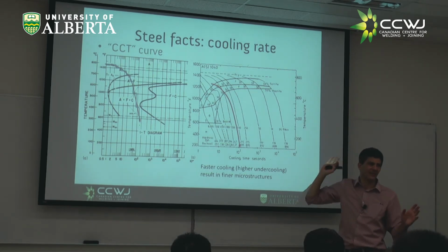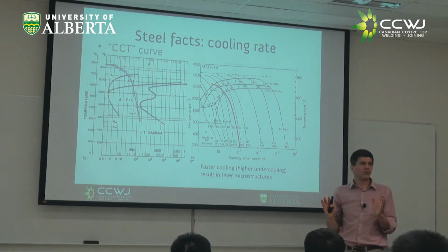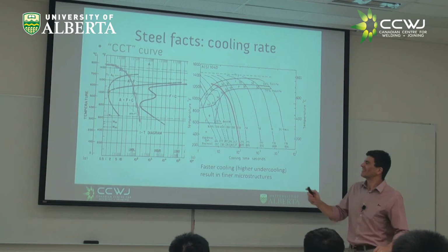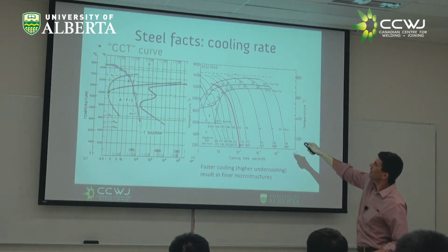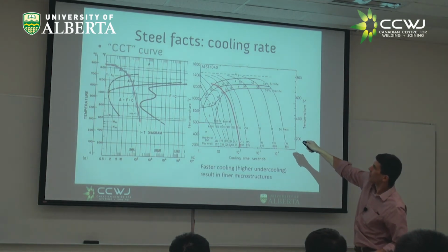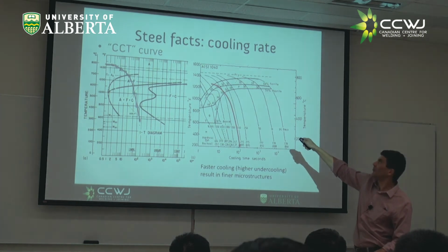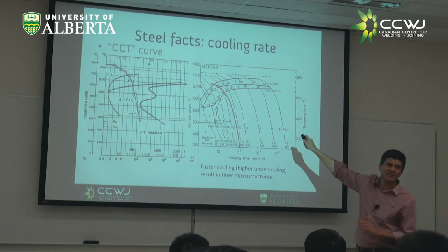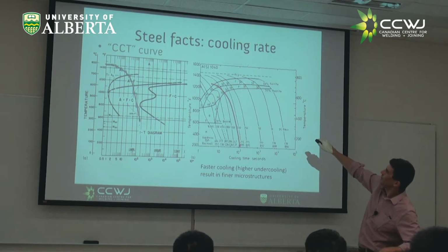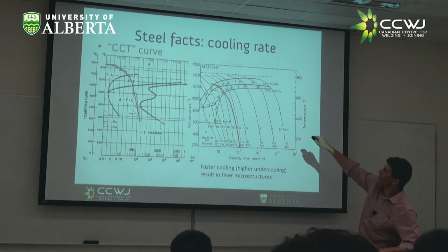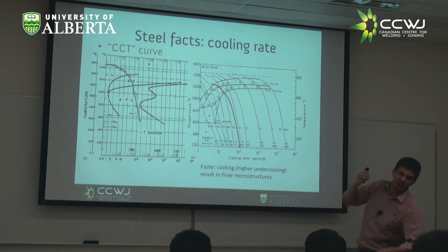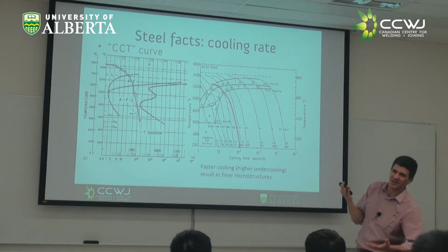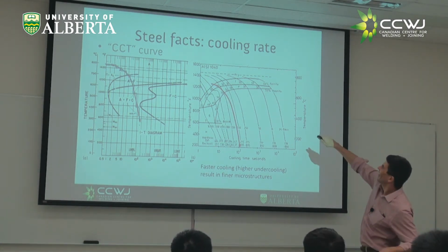Yes, I have austenite. And again, they don't mean to throw you off, but they do a pretty good job at it, right? They take for granted you would know that if you have pearlite here, you had some austenite in here. Actually, look at this. This is a pretty awesome diagram. See, it says 50 here. It says 50% ferrite, the other 50% being austenite, right?